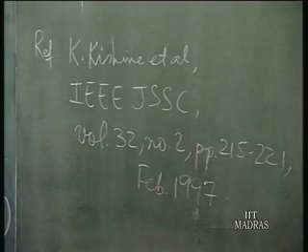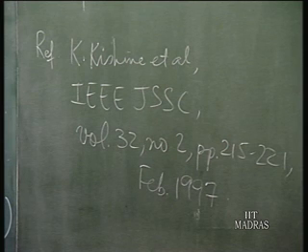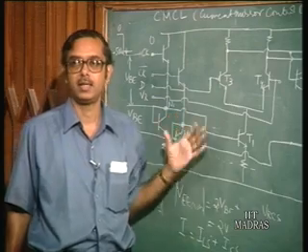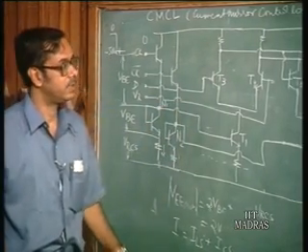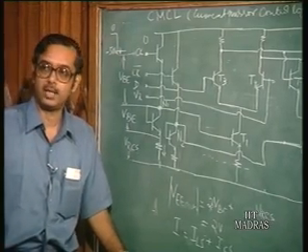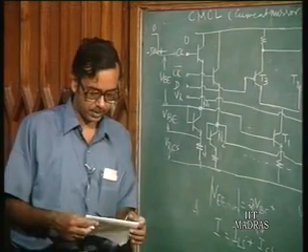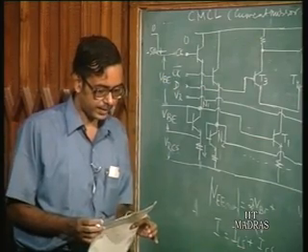Okay. So, this is a new logic family, a sort of variation of the ECL, where you achieve a lot of reduction in power dissipation, which is the stumbling block in ECL. With this advancement, one hopes one can really realize LSI level circuits using ECL. That is what they claim in that paper.